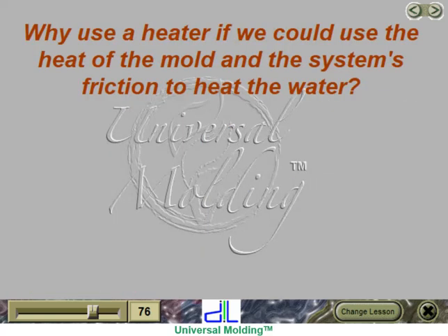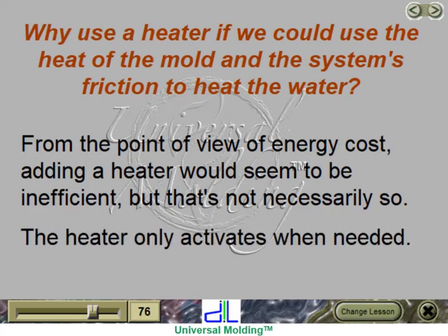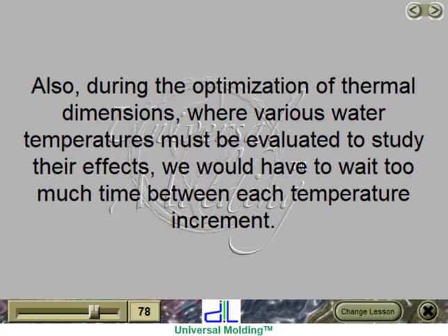Why use a heater if we could use the heat of the mold and the system's friction to heat the water? From the point of view of energy cost, adding a heater would seem to be inefficient, but that's not necessarily so. The heater only activates when needed. We can safely assume that, during the startup of a mold where the chiller water reaches 30 degrees centigrade and we want to operate at 90 degrees centigrade, it would take too much time to reach our operating temperature if we depended upon friction and the heat of the mold. Also, during the optimization of thermal dimensions, where various water temperatures must be evaluated to study their effects, we would have to wait too much time between each temperature increment.